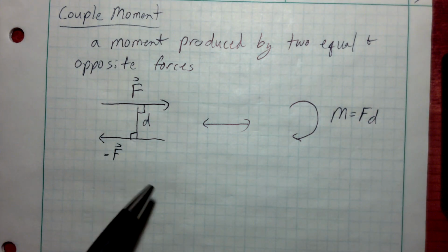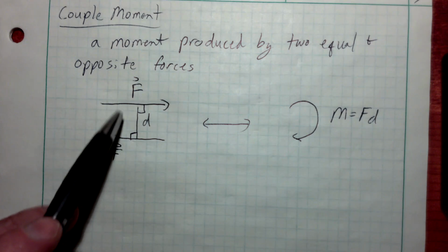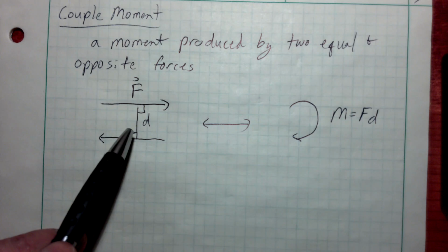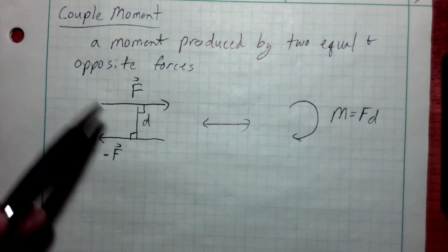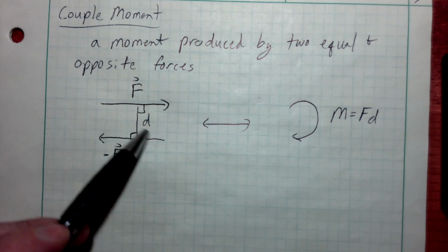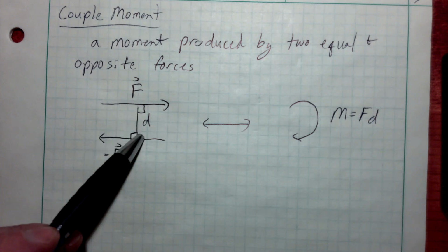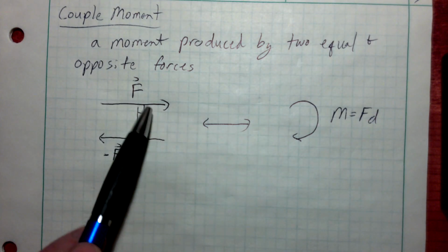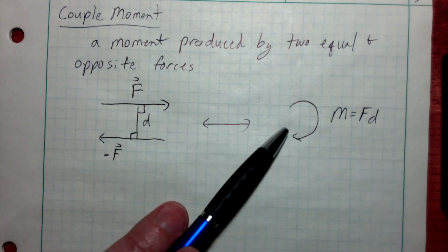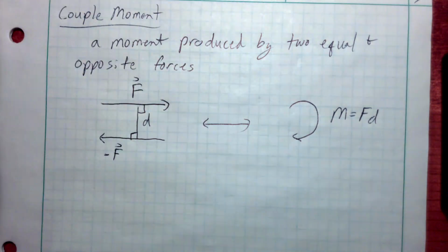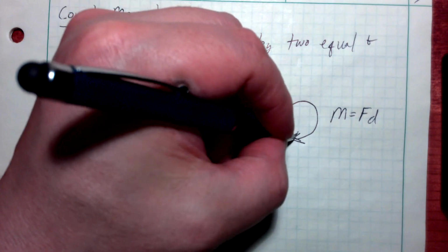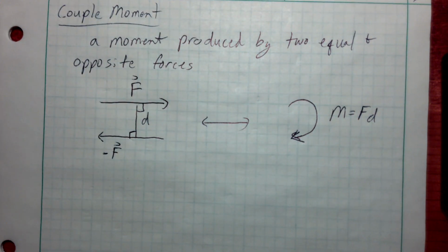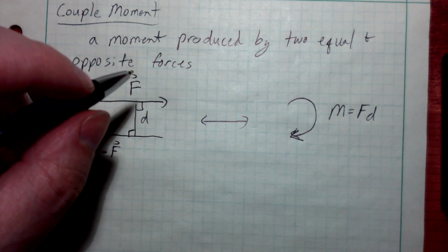And also, if I'm drawing a free body diagram and I've got two forces equal and opposite, a set distance apart, you can actually remove them off the free body diagram because they have no net effect. The sum of these two forces is going to be 0. However, you do have to replace them with the moment, or the potential rotation, caused by those two forces. So this is a common thing that you will encounter.